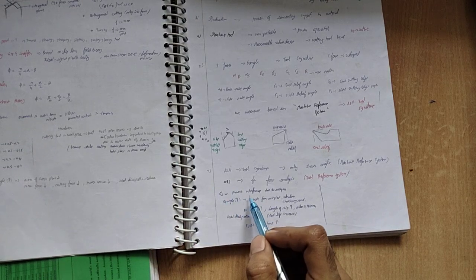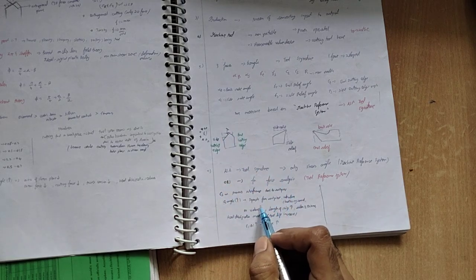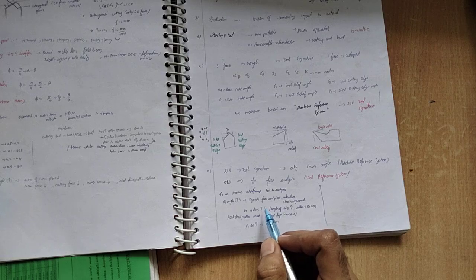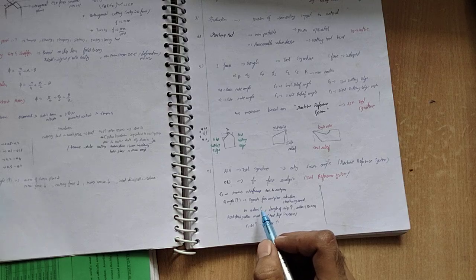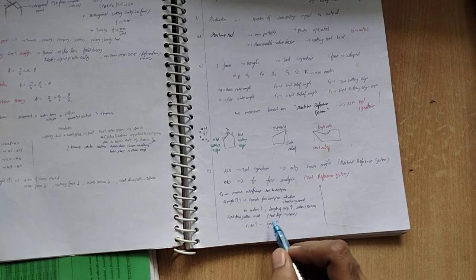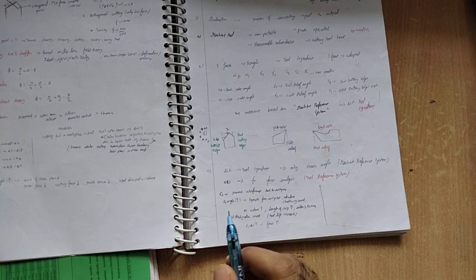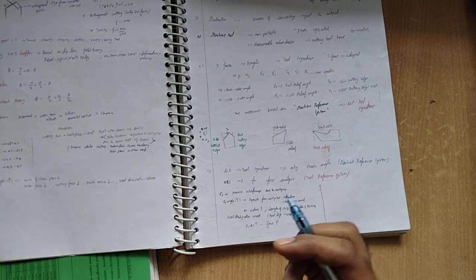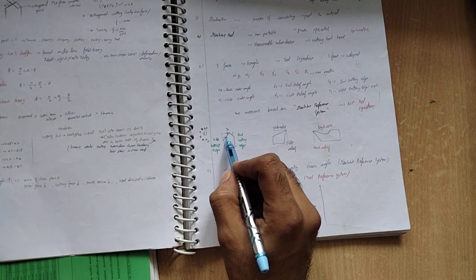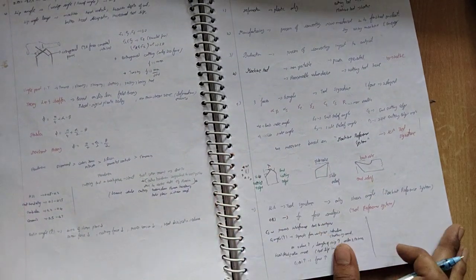The side cutting edge angle prevents interference to the workpiece. When the side cutting edge angle increases, separation from the workpiece will definitely be there. It also induces a chattering sound, and the length of the chip increases, and with the tip, heat dissipation flow increases, and tool life also increases. But the main thing is that separation from the workpiece will be much higher, and the vibration will be much higher. Since the edge will go like this, we need to give a lot of force. I think you can understand.